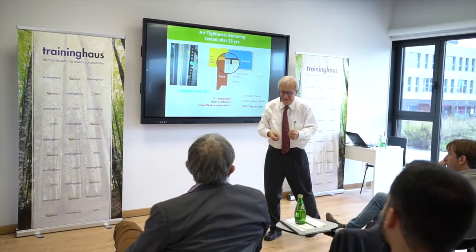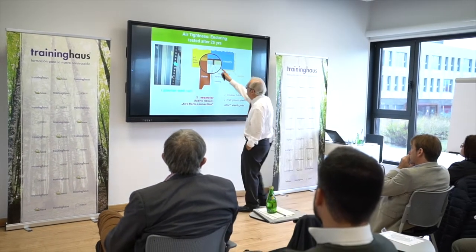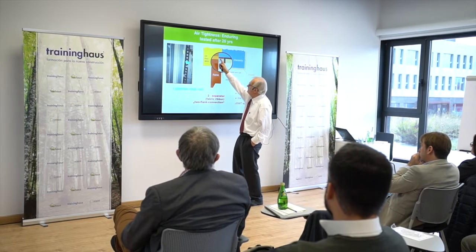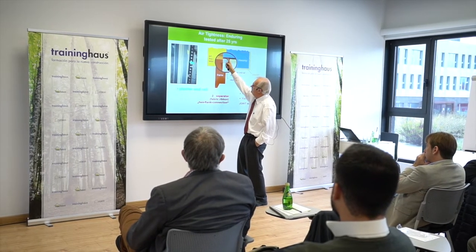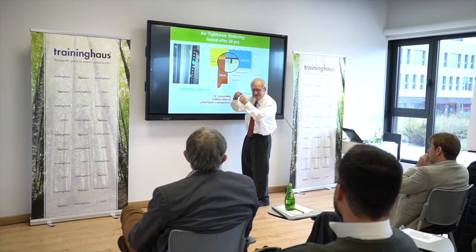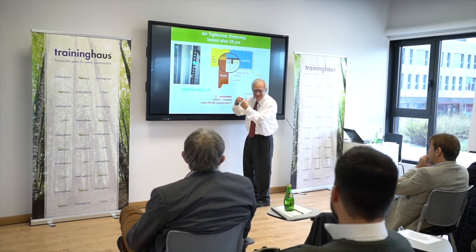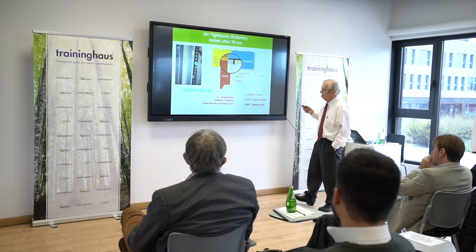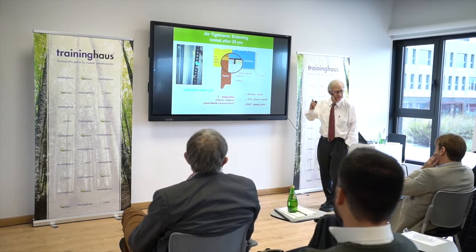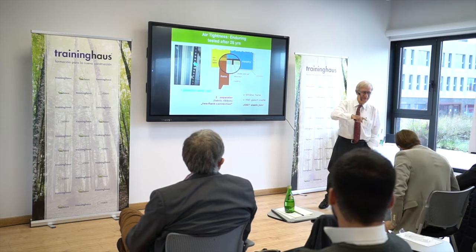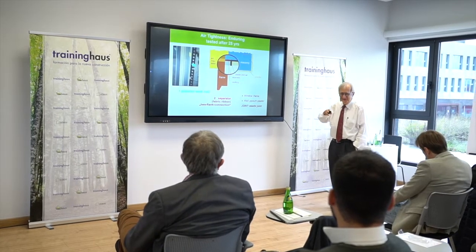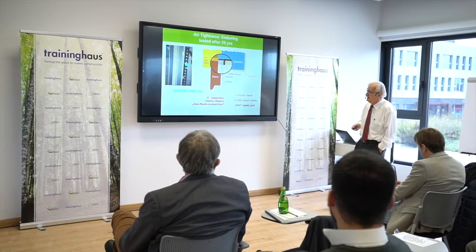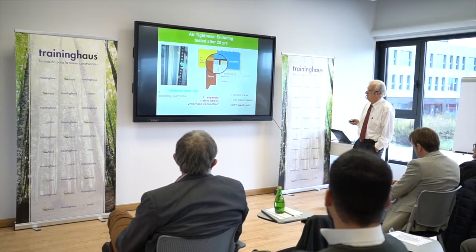No, they will work. The reason why they rip is if you do not have the separator here. Because then it will also be fixed to the wall, and the space it has to bend is too small, so then it will rip. So that is an important part of that kind of connection. Very easy to do if you know how to do it. It's also not new. It's well known in the building industry for a long time, but it somehow got forgotten, and that's the reason why in many cases it's being done the wrong way.